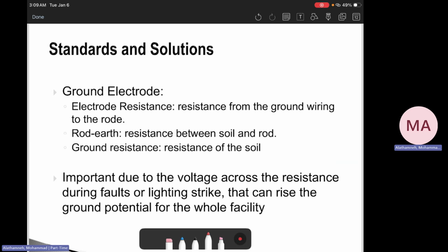Soil resistivity can be high in many areas, especially in dry or rocky soil. This means the ground electrode resistance can be higher than expected unless it has been designed properly for that. Then we need to pay attention to electrode design, not just install one rod and leave. Lightning in the winter season can create transients and ground potential rise, and can cause equipment upsets, especially on rural feeders.